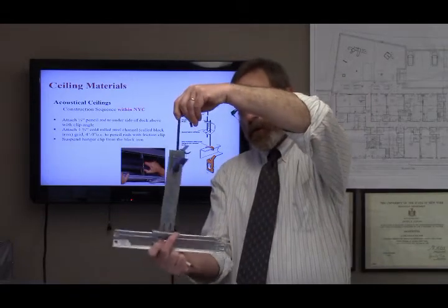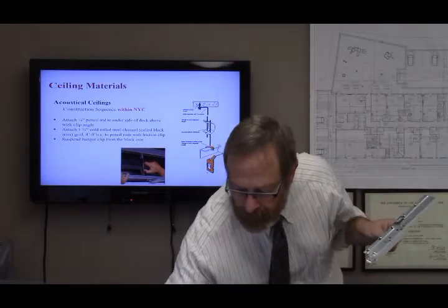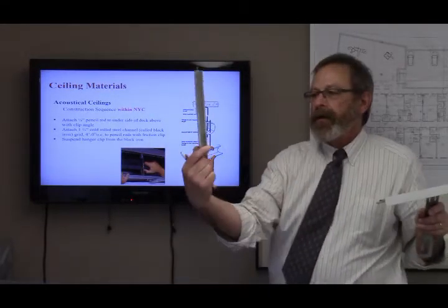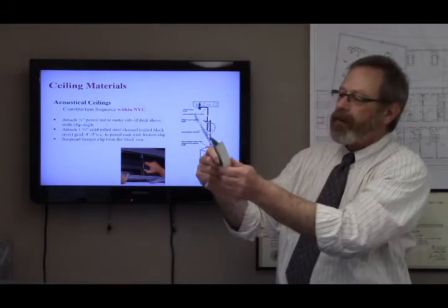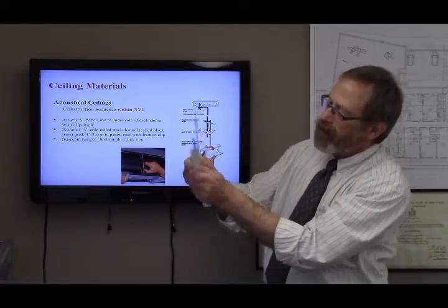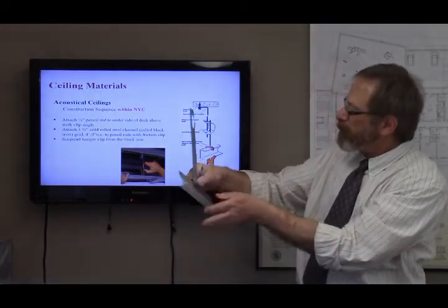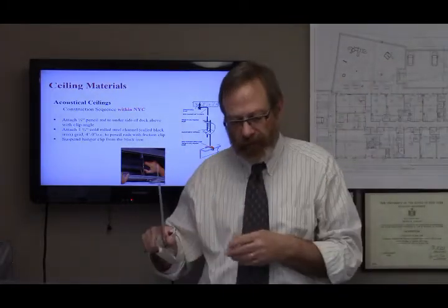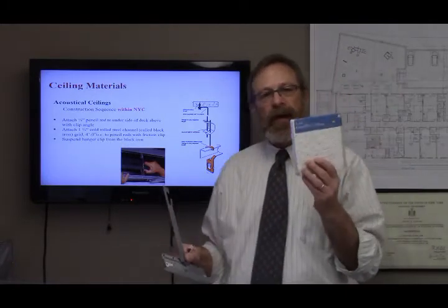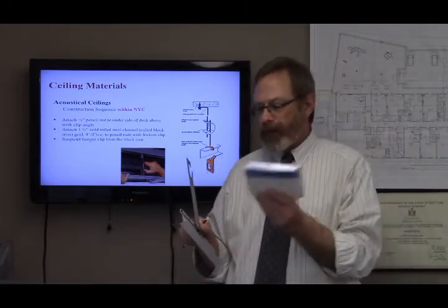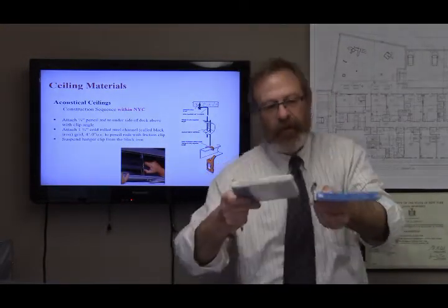To the hanger, we are going to attach a ceiling tee. Looks like this, they come in long runs, 12 foot. It's securely attached to the hanger. This is what it looks like. These are spaced every 24 inches on center, because our acoustical ceiling tiles come, as I said, 2 foot by 2 foot or 2 foot by 4 foot, and they're just going to rest there and there, just like that.